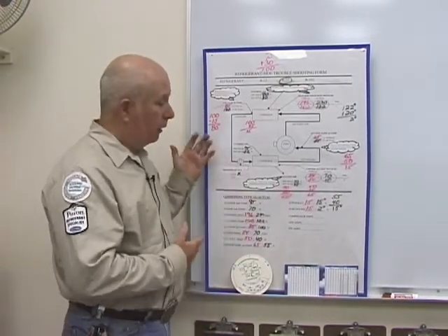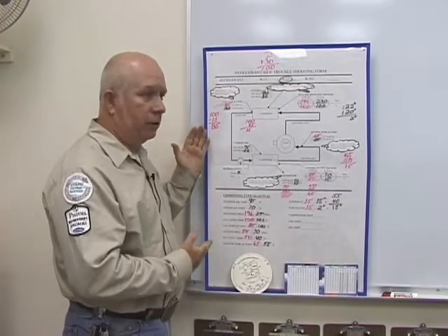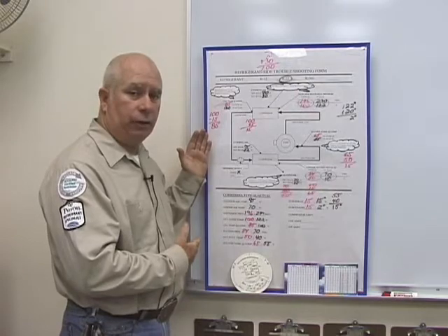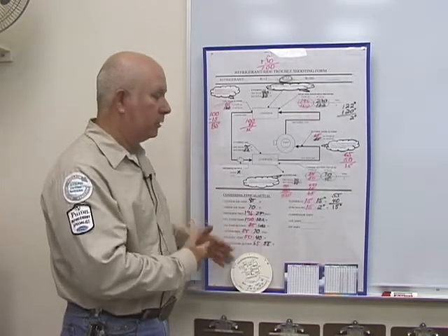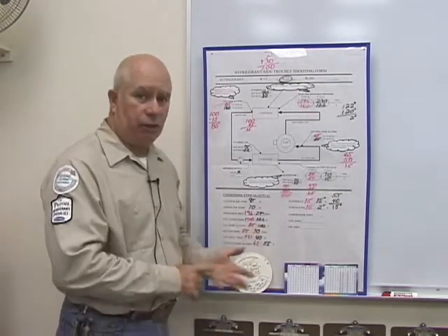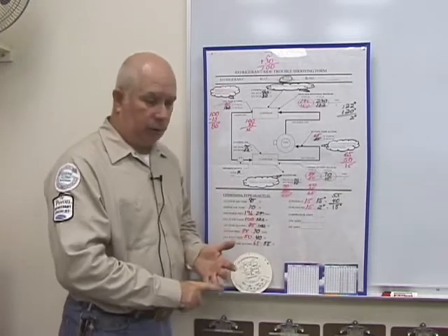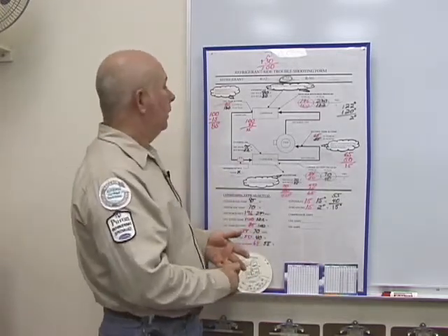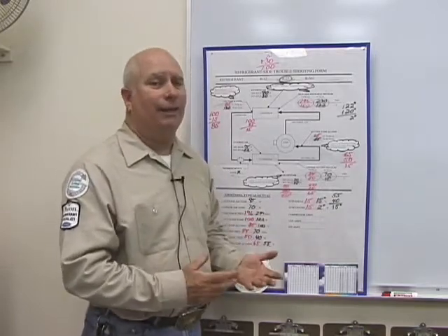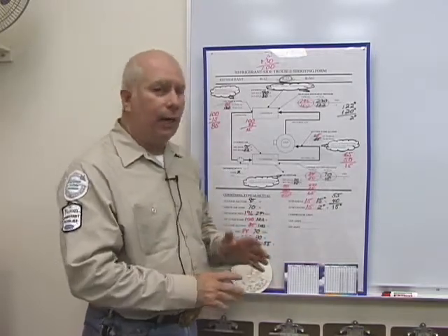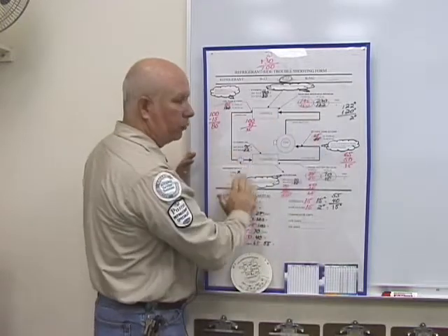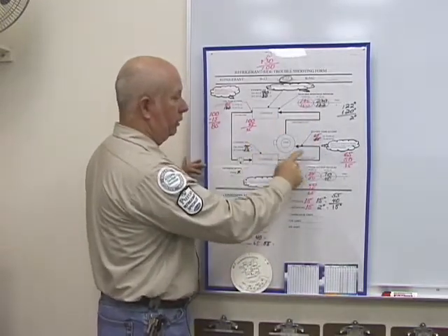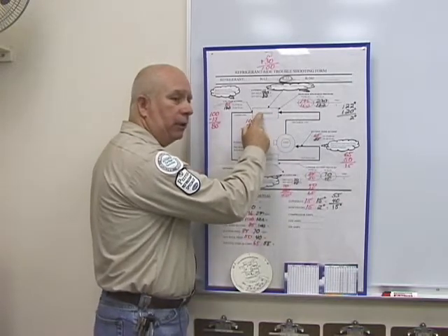Again, ask yourself, can I do this without the instructions? Do I know what all the terminology is? Do I know what it means for typical and actual and saturation temperature and discharge pressure and temperature and liquid temperature at the condenser? Do I understand how the system is working? What lines are discharge? Which one's liquid? Which one's suction? What three things happen in the condenser?